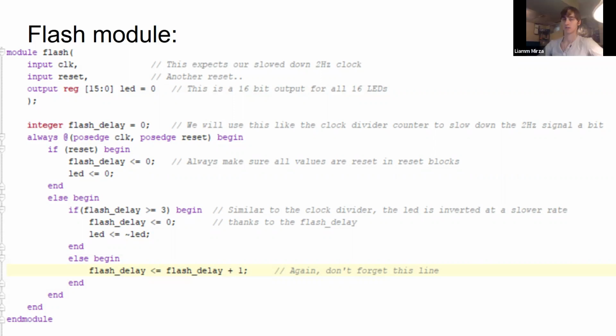It's not always concurrently, it just means it doesn't matter that flash delay should happen before LED. So it just means it should happen in the same cycle, timing wise. I think in general though, unless you're in an always A, B, C, D situation, you should always use a non-blocking operator. Yeah. There's very few cases in this course where you'd use an equal sign, I think.